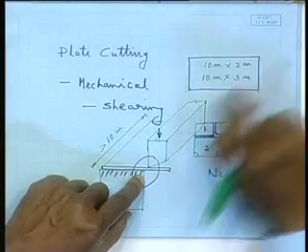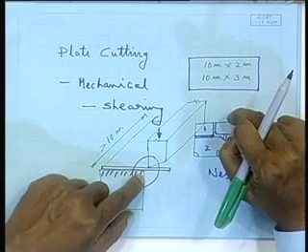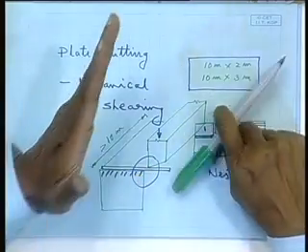And also, in mechanical shearing cutting, they are all straight edges we are cutting. So, in 99% of cases, all these edges which have been cut will be subsequently welded to something for fabrication of some structural component. Once they are welded, whatever work hardening took place is nullified. So, that problem is not there as such. It is not of concern, we can say. Like in the case of shot blasting, it was a matter of concern, but here it is not so.